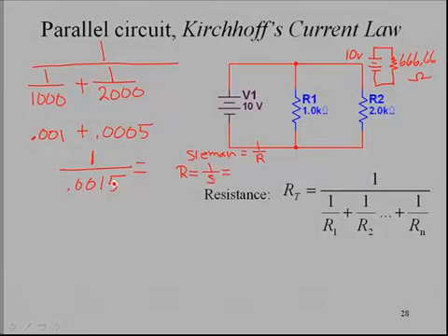And so we did this so that we could calculate the parallel resistance. So we did 1 over S, and that's what gave us this value. So essentially when you calculate parallel resistance, what you're doing is adding up the total conductance and then taking the reciprocal of that total conductance and getting the resistance. Now, your book doesn't go into this. I'm not going to make an issue of this, but I just wanted to give a little background on why this particular circuit actually works. If you don't want to know why it works, that's okay, but just be able to use this formula.